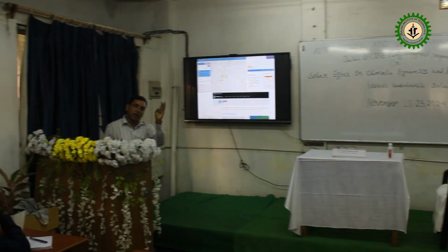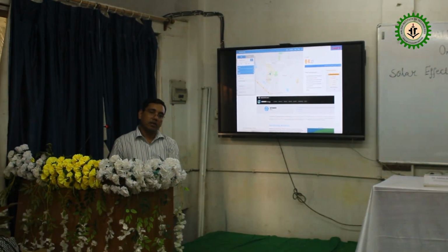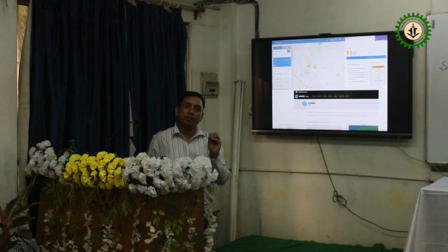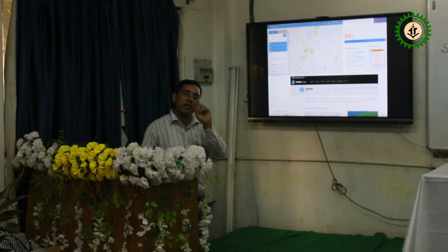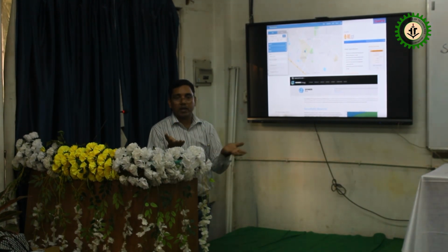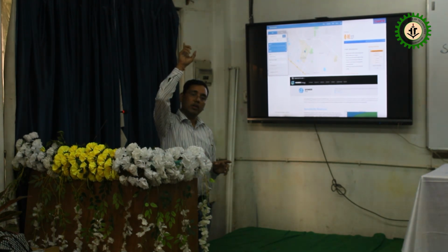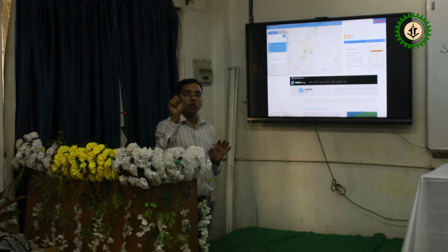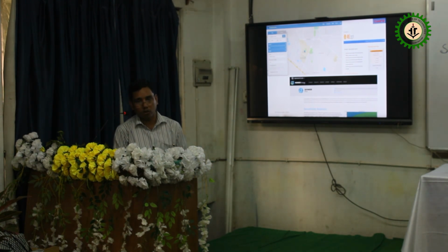What is the solar radiation available, what will be the power output. Any real time, real data? Real data, simulated data. It will be correct up to 90 to 95%. If you do not do an actual installation, maybe in your lab some panel is there, you can practice on that. From Homer this much is coming, you go on your rooftop and see the performance coming according to that. Maybe 4.3 is coming, that may come to 3.9. Near about average power, I can say for 4 kilowatt it will come in.